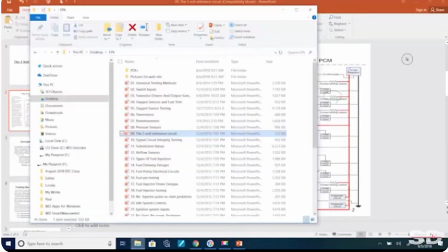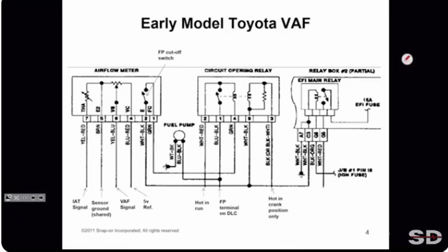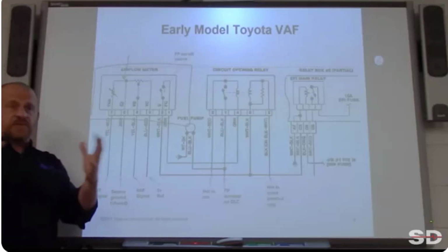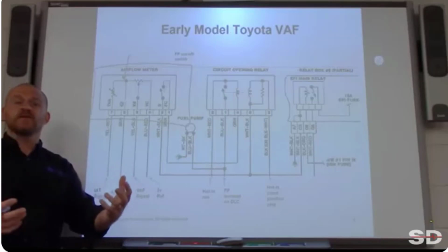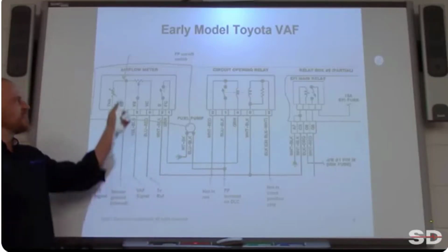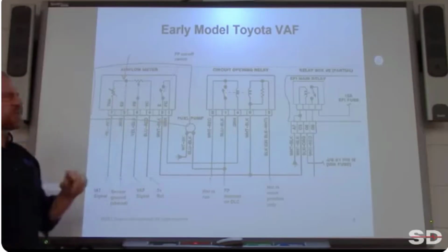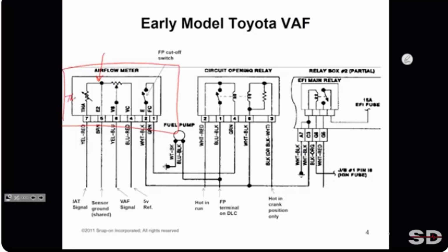Let's go back to 12. So, do you understand with that conversation, all we're looking at, just keep your eyes focused right here. Don't look beyond that red square. Do you understand that this shared wire could potentially be, we have 2 different sensors and we can share a reference, we can share grounds, but certain things we can't share a reference with. So what does that make that shared wire in the conversation we just had? This being a thermistor and this being a potentiometer, we cannot share the reference. This has to be, no question about it, it has to be the ground for these 2 sensors.